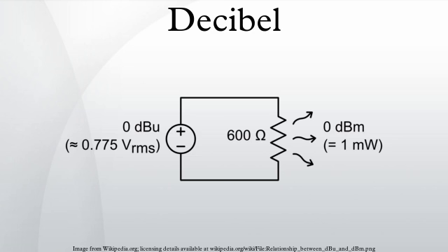There is no fixed conversion rule between dBiC and dBi, as it depends on the receiving antenna and the field polarization. dBq, decibel quarter wave: the forward gain of an antenna compared to a quarter wavelength whip. Rarely used, except in some marketing material. 0 dBq equals about 0.85 dBi. dBsm, decibel m2: decibel relative to 1 square meter, a measure of the antenna effective area. dBm⁻¹, decibel relative to reciprocal of meter: a measure of the antenna factor.